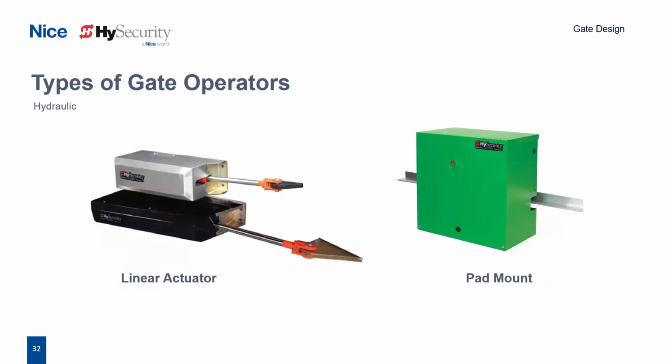The other option is hydraulic, used in industrial installations with wide and heavy gates that are intended for continuous duty and are more powerful and better performing with their hydraulic motors and high levels of torque. These are not going to be susceptible to electric failures, making them the reliable choice for mission-critical applications. Also relatively simple to maintain and with a longer lifespan. However, there is going to be a larger upfront cost versus the electromechanicals. And these are the best options for cold climates as they are rated to 40 below operating temperatures.